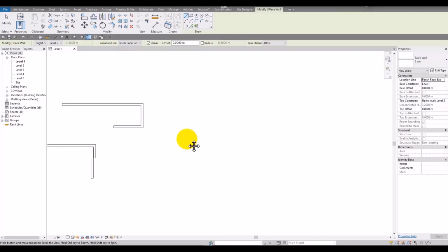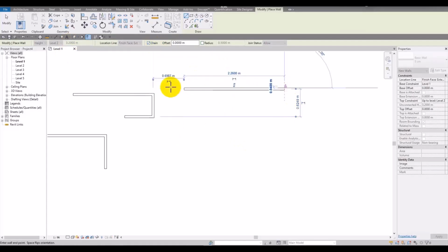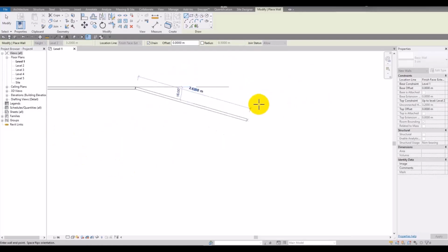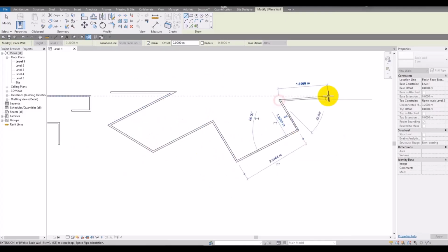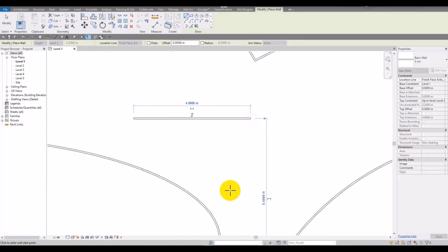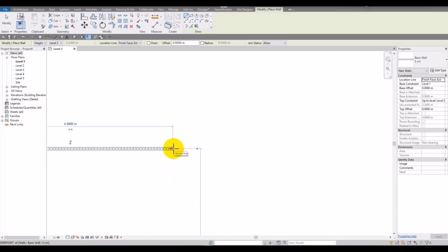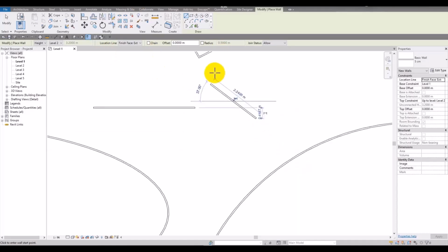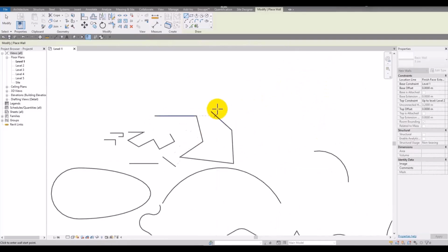Okay, there are some other options which can be useful. For instance, chain. What is it? It means when I draw this wall with a click, the preview of drawing the next wall will appear. Then I can keep going to draw these walls like a chain. Now when I deselect it and click here to draw, as you can see, it will be finished. It's not possible to continue drawing. And to have the next wall, I need to do it again, right here or somewhere else. And if you want to have continuous drawing, you can select the chain to continue the drawing like this.